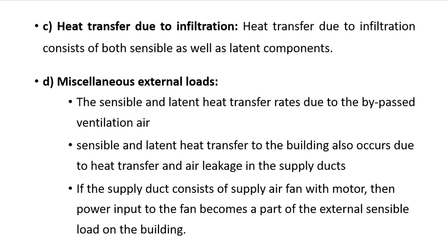So we have to reduce the temperature and humidity level of that fresh air. That is an external load. Then sensible and latent heat due to the air leakage in the supply ducts and return ducts, as well as the heat load associated with the working of supply air fan motor and return air fan motor.